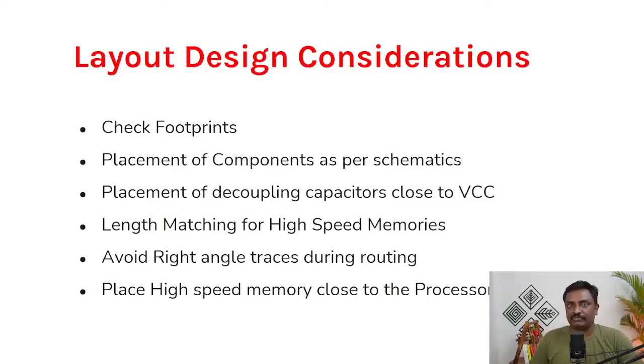When you want to manufacture 100 or 200 products, in that case you can go with the stencil, and there are separate assembly houses for manufacturing. In India it is there. Even in China you can go for an assembly house, because an individual cannot purchase an oven. It will cost you around 1 crore rupees.